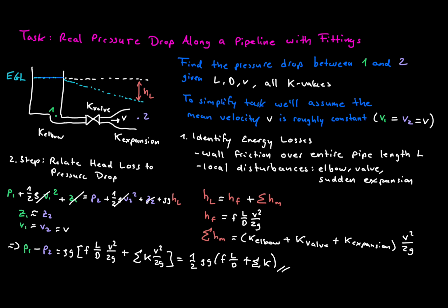Substitute this back in and the pressure drop becomes delta P equals 1/2 density V squared times the quantity fL over d plus the sum of k values. That's the full picture. Friction plus fittings. The complete real-world pressure drop.